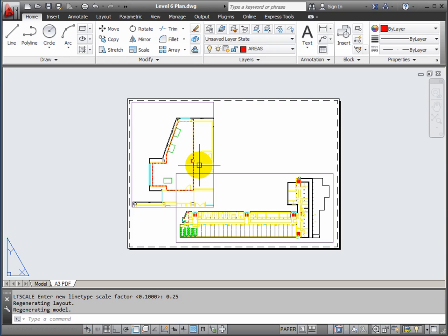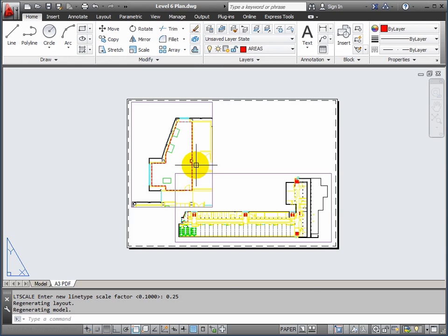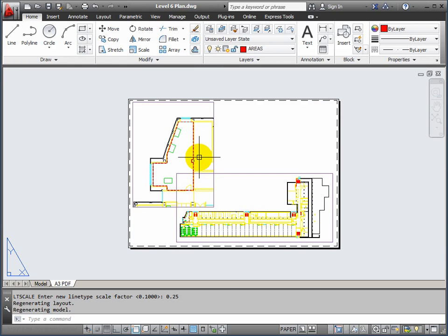You can force lines to have individually different scales, but it gets quite messy, and I probably would avoid it if you can. That's done through the properties, change properties tool. So that in a nutshell is how you set the layout up. What we'll do is we'll break off here and restart on the line weight issue in the next section. Okay, we'll stop just now.